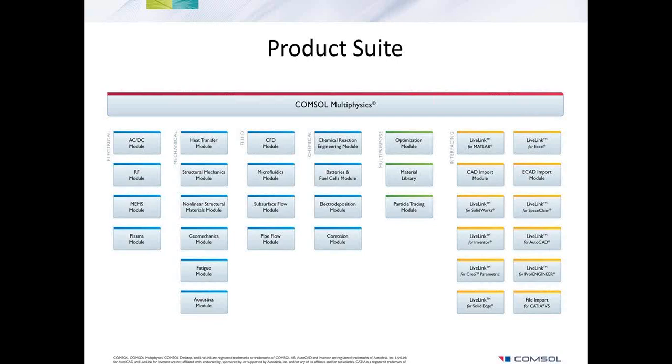So in order to address these differences in scales in your modeling geometry, these advanced options are available to absorb waves. To address the second question, how we determine the appropriate thickness, that's typically based on the wavelength. So roughly speaking, you would want to have a thickness of one wavelength.